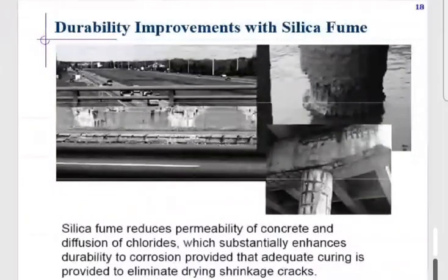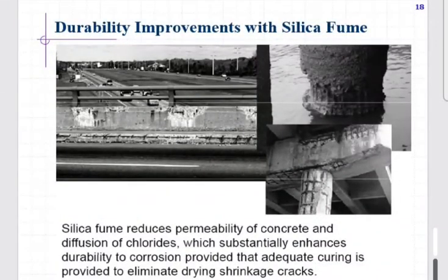I repeat again, there are two things. One is physical, another one is chemical. Physical means there are micropores within the cement. Whenever cement to cement particles are connected, there are voids. जब सीमेंट का पार्टिकल सीमेंट के पार्टिकल के साथ मिलता है जी, तो still there are voids actually at micro or nano level. Those should be filled so that the pores should be minimum.